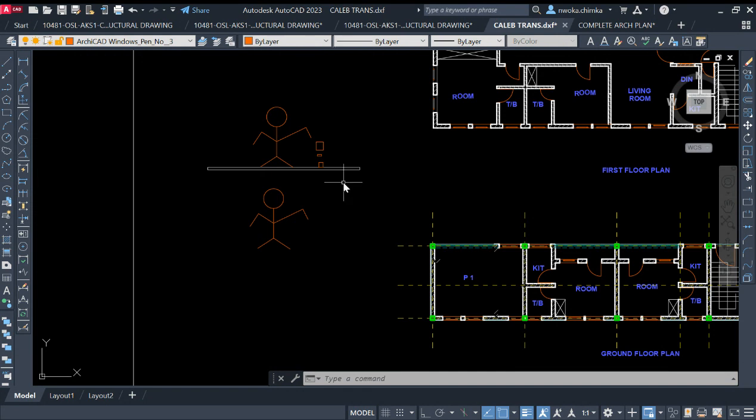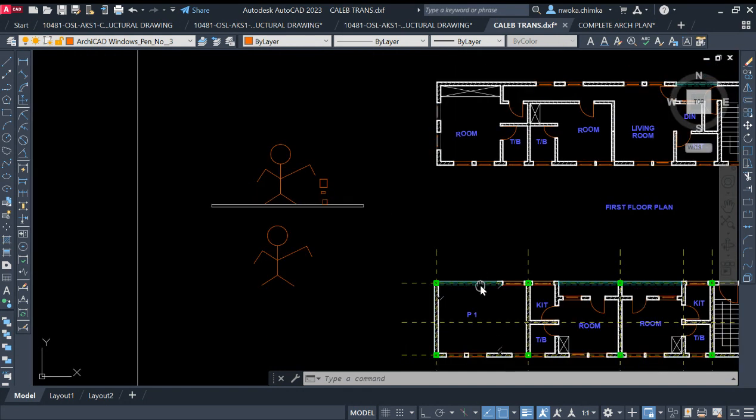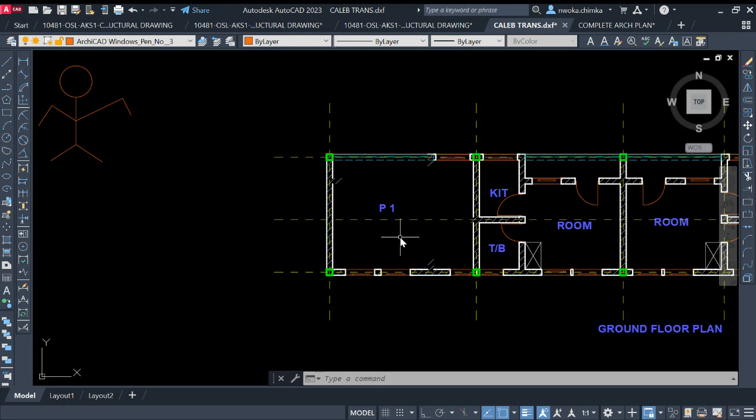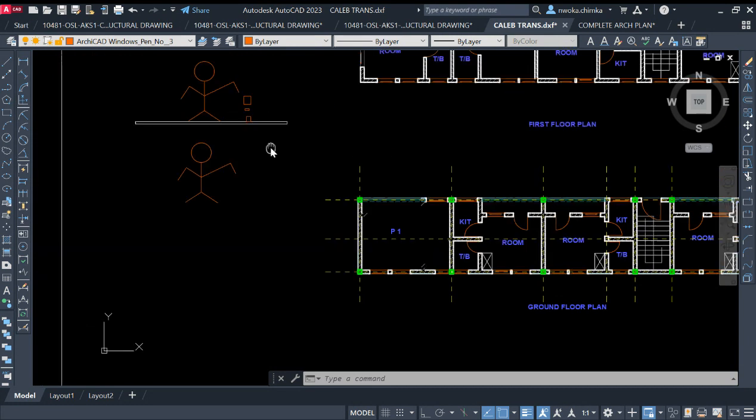Two, when you're performing your slab reinforcement spacing during the construction, they didn't follow your slab prescription. What I mean by your slab prescription is that if you specify that the spacing of reinforcement should be 150 millimeter each, and they went ahead and gave 300 spacing each,